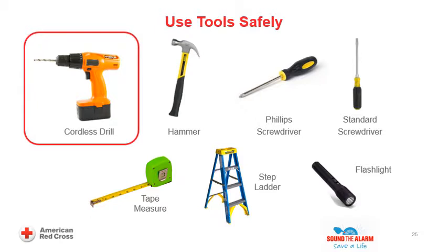Operating precautions. Never wear loose clothing or jewelry when using a cordless drill. Tie long hair back or secure under a cap. Always wear safety glasses or goggles when drilling. Do not operate a cordless drill in the presence of flammable fumes. Avoid using a cordless drill in wet conditions. Use the correct drill bit for the type of material to be drilled for the task at hand.